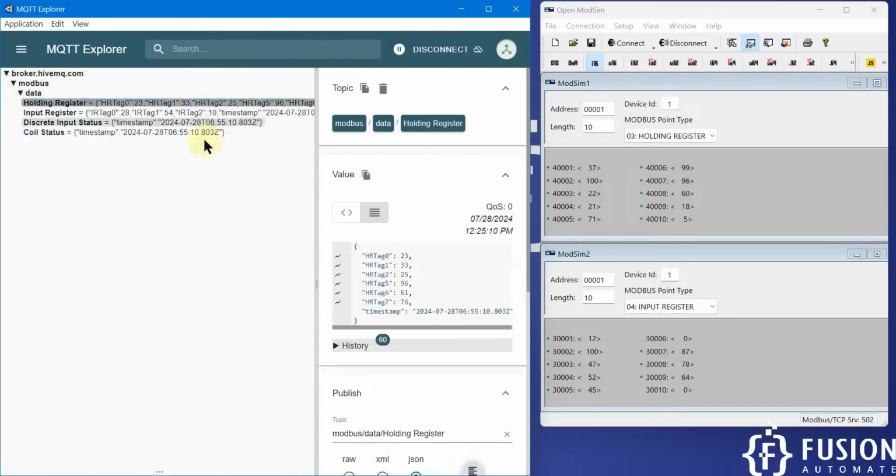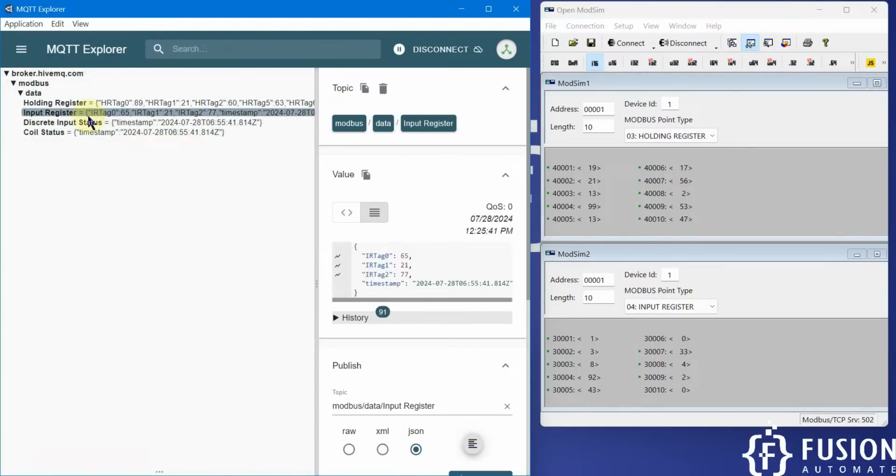Okay, and then after that you can integrate this data into any system, and also you will get the timestamp. You can see every second we will have data. Okay, 50, 18, 19, 20. Okay, here also you can monitor your timestamp. So this is how you can use JavaScript to create your own unidirectional Modbus to MQTT converter, or you can say Modbus to MQTT publisher. Also here you can read the input register data. Okay, you can see the first 3 input register data is available here.